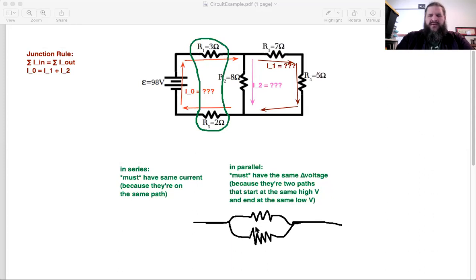On the other hand, if you take a look at this circuit, this network I just drew, if you're walking along this path, you don't go through both of these resistors. You have the option of going through one of them or going through the other one. So parallel resistors are sort of mutually exclusive in that way. Any path you draw is going to go through one or the other, but not both. Whereas in series, any path you draw has to go through both of them or bypass both of them. So both of them or neither one. So that's one way you can check if they're in series or in parallel.